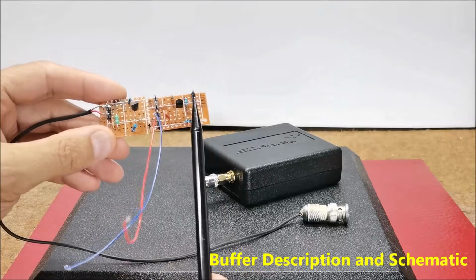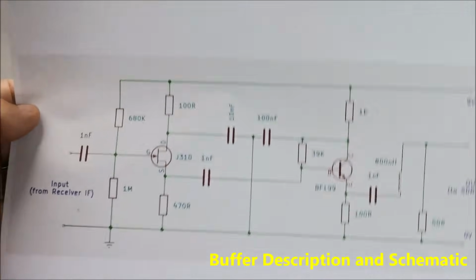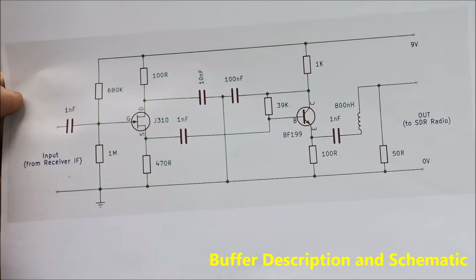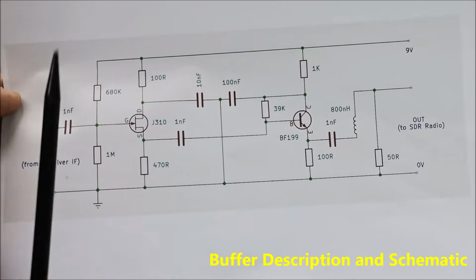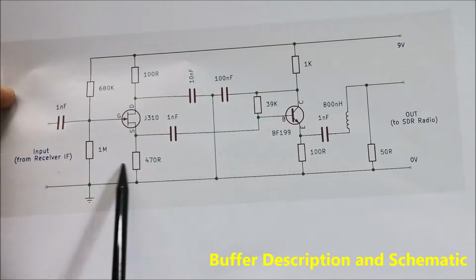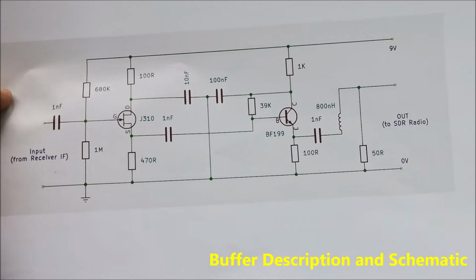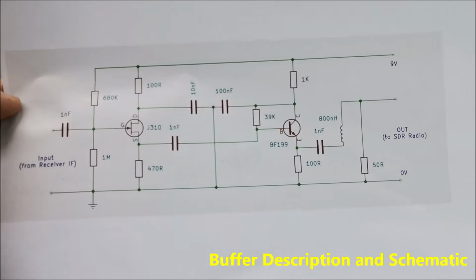Therefore, the buffer amplifier shown in the diagram below has a very high input impedance and a low output impedance, so it does not affect the received signal at all. The buffer has two active stages: a JFET source follower to present a high impedance to the IF filter and therefore minimize any loading on the main signal path of the radio.